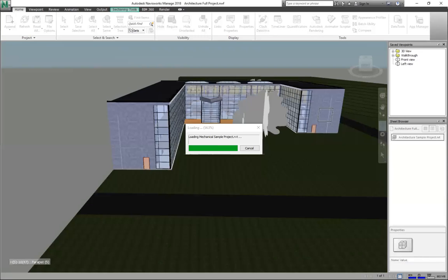there should be a BIM execution plan, which is to note out the responsibilities of everybody, the tools that we use, the critical namings and characteristics that we use. Of course, in projects, we have standards of measurement, we have standards of contracts and all of that. So the BIM execution plan helps to itemize all of this at the beginning of the BIM project, so that when that workflow is going on, there will be no distortion between the information being sent from construction project stakeholders.